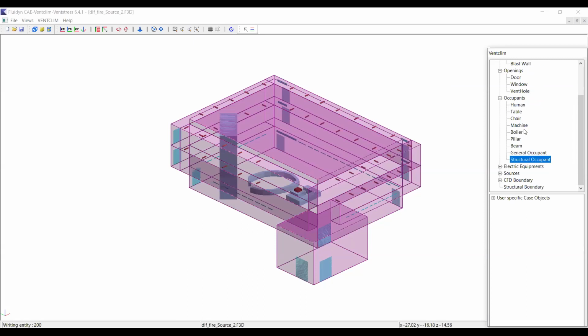For example, from a CHT point of view, the fluid is coupled with the thermal. Similarly, from a fire point of view, it will couple with the stress as well as thermal. From a vent point of view, it couples with stress. That's an FSI case. So based upon the application, the fluid is coupled in different ways with the structures.